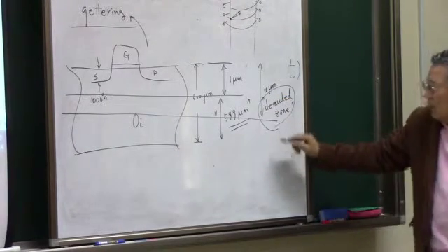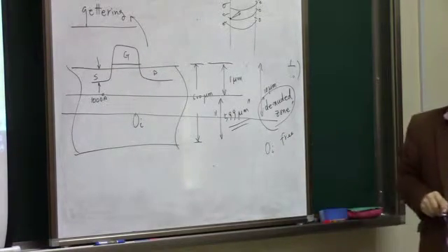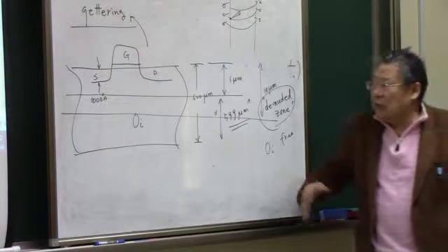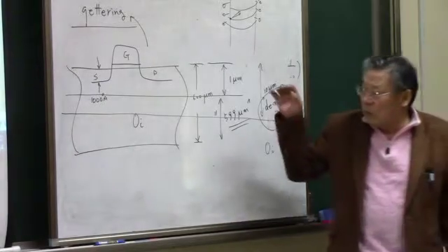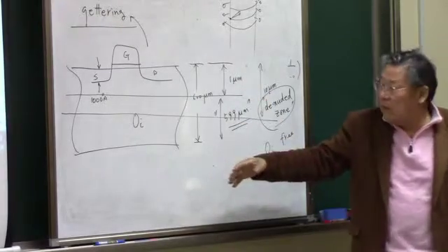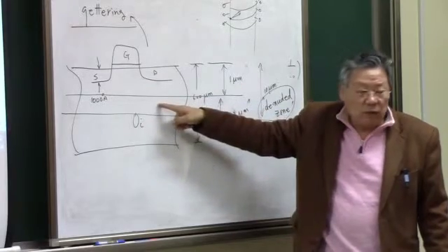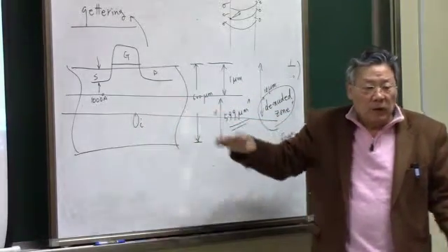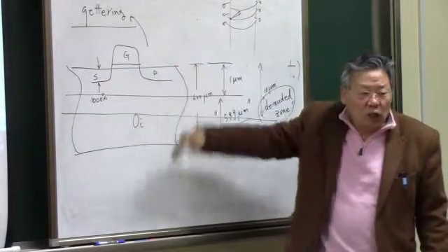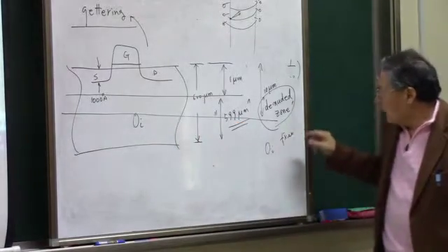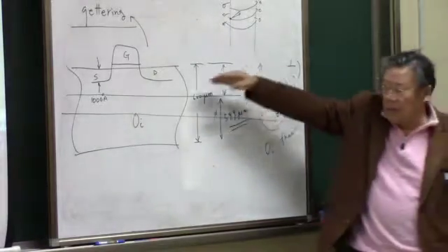Means interstitial oxygen free zone. Now how do you get it? You use the heat cycles, heating up and cooling down, and heating up and cooling down. Then this surface has a different potential with respect to the inside of this wafer. So that potential difference drives the oxygen, surface oxygen, into the bulk. Okay, so that we can create some oxygen-free denuded zone from the top.